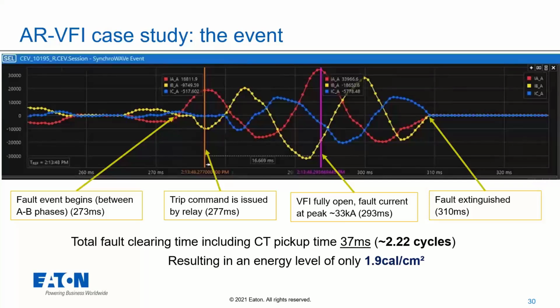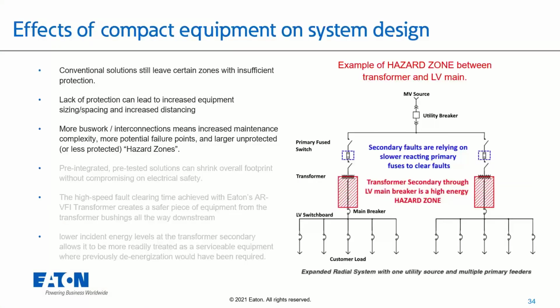At this point of the project, it can be pretty difficult to obtain a replacement piece of equipment when you're already in the commissioning phase. So in this case, there's just the singe on the buswork I was mentioning. They just cleaned that up, checked everything, retested it, and they were able to re-energize without having to replace the equipment.